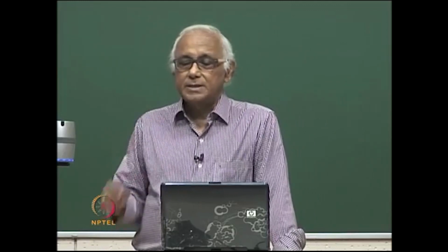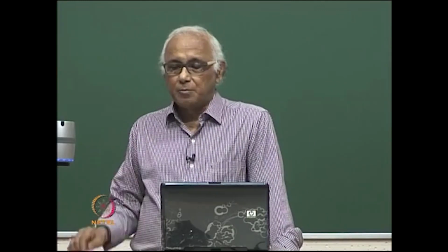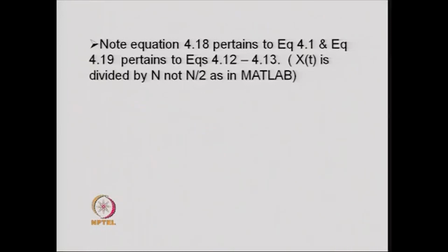Then join the center of those bars in order to get the power spectral density function. All these things have been discussed before, so I do not want to repeat them. Only I wish to mention here that we are able to define the power spectral density function of ground motion in this fashion because we assume the process to be an ergodic process, and therefore we looked at only one single time history record, and from there we are constructing its power